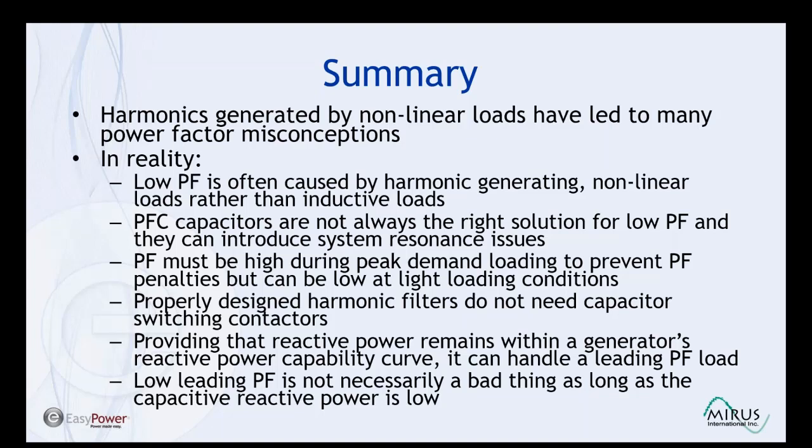Properly designed harmonic filters do not need capacitor switching contactors, and providing that reactive power remains within a generator's reactive power capability curve, it is certainly capable of handling a leading power factor load. And low leading power factor is not necessarily a bad thing as long as the capacitor reactance is kept low.